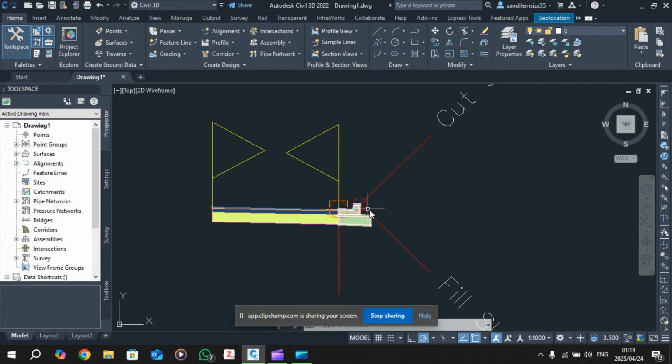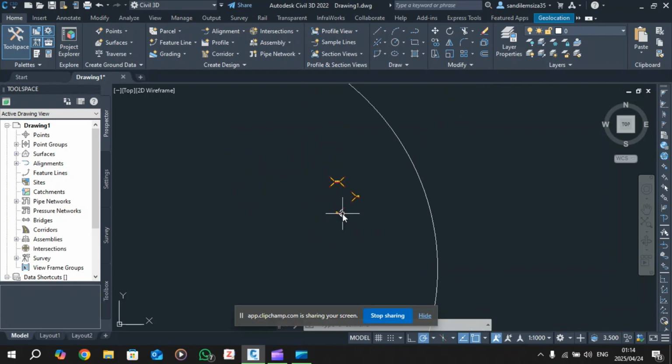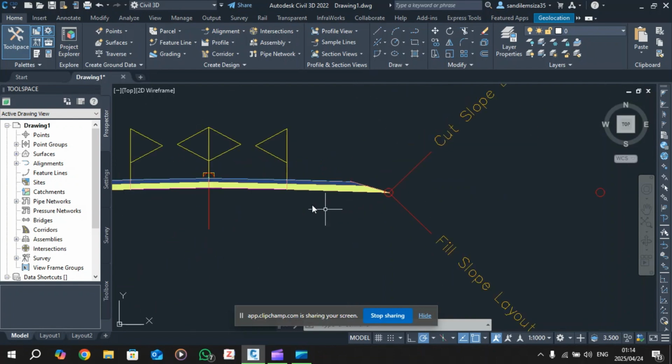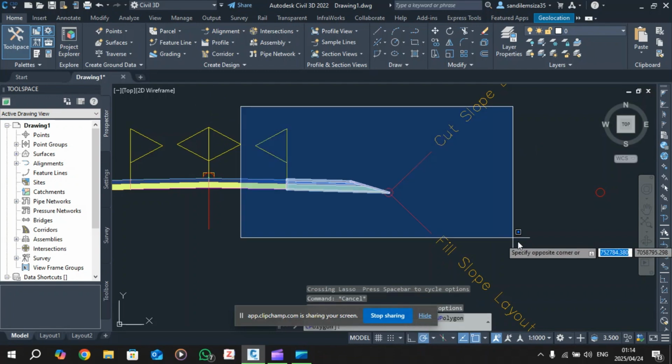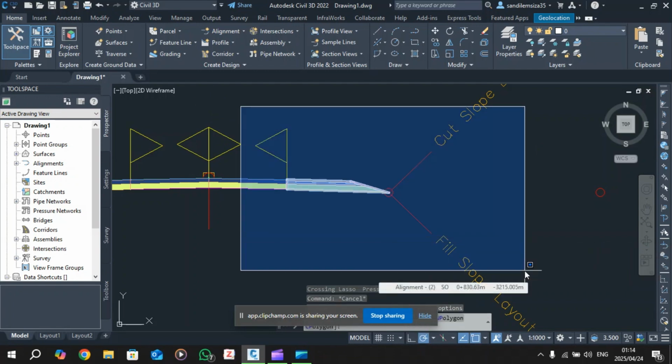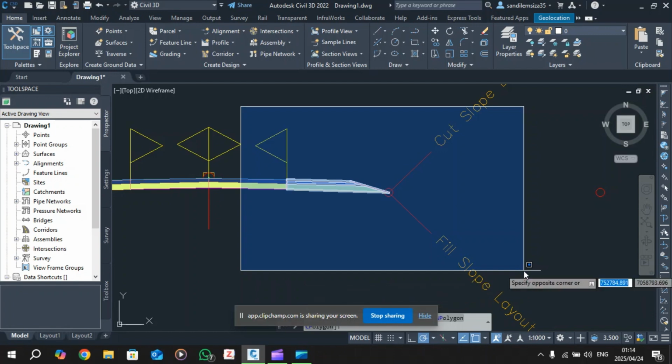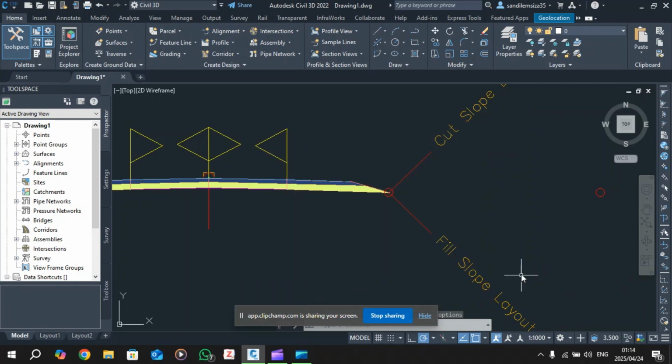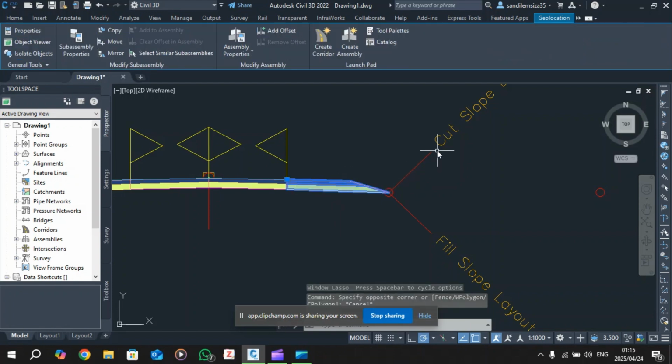everything to the right except for our lane. What do I mean by that? If you go to ours quickly, our curb return is essentially this part right here. Our curb return is basically this bit, where it's highlighted in blue: our lane, the shoulder, and the cut ditch. On the right side of our curb return, we just need this and this, not the lane. The lane will fall to the left side of that assembly.